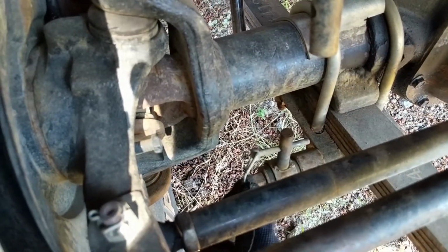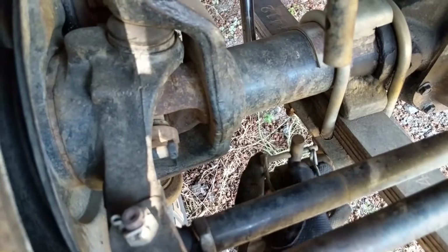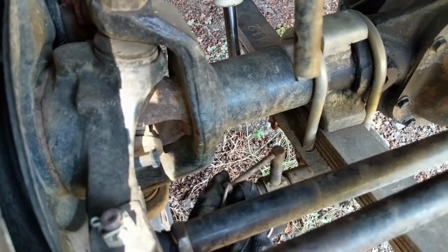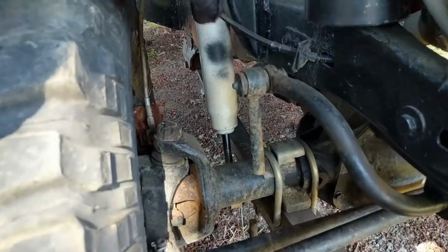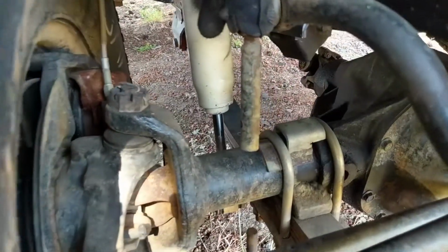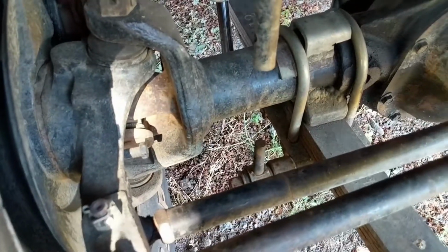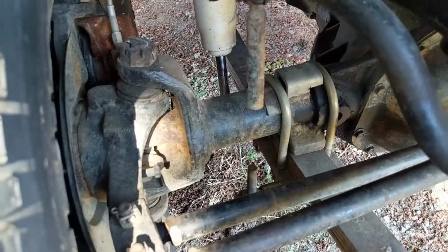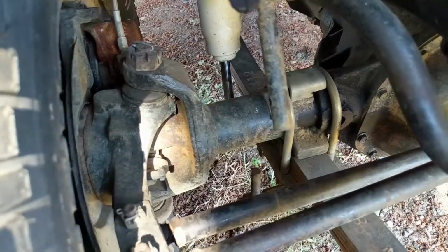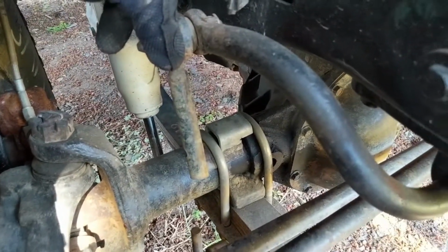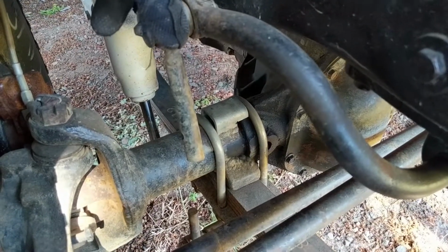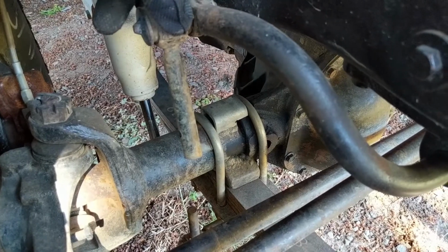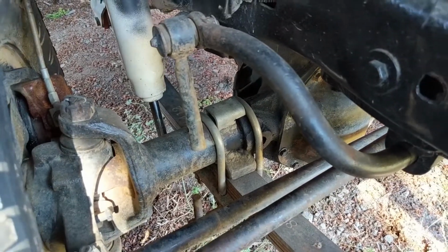Both sway bar end links on the front of the Jeep have been modified to be disconnected and reconnected for off-road and on-road performance. With the sway bar disconnected, our links are now separated, and we're no longer tying an unsprung component to a sprung component and offering stabilization of the vehicle. So this allows more movement of the suspension from the chassis to provide better articulation and flex in an off-road situation, and in that case, more flex is what gives you more traction.